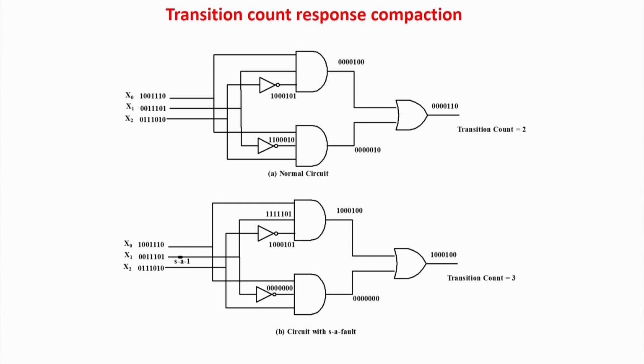So in fact, what I mean to say here was basically when you get the output, we do not compress it. Rather we go for compaction. And there are a lot of compaction techniques. Two very preliminary ones I have given you an idea of, but for many of the cases, just like we are very successful in compression, for most of the cases aliasing does not happen, or very rare aliasing happens. So with slight modification in technique, like if you are using LFSR based compaction or some other methods of compaction, the aliasing effects are very rare, very less, and we can actually have a very small bit width representation of the output to get a very good fault coverage.